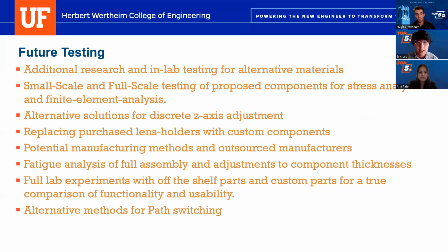If selected, these are the proposed steps to improve our current ideation. In lab testing of prototype models, we'll provide additional research and proof of our material selection and current thickness for our plastic components. This would show whether or not we over-designed our components, in which case we reduce the amount of material we're using and lower production costs. Additionally, if our stress values prove to underestimate the real forces, we'll return to concept generation and/or material down selection, depending on the degree and the style of failure.